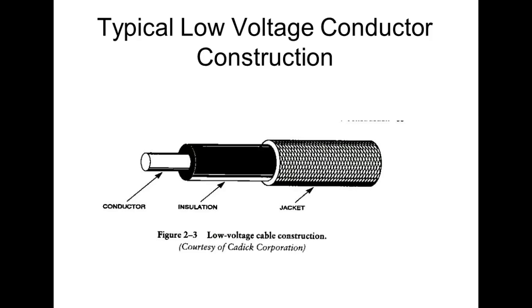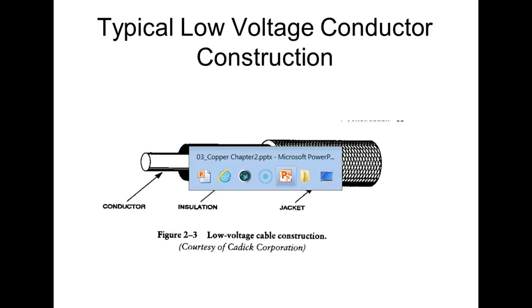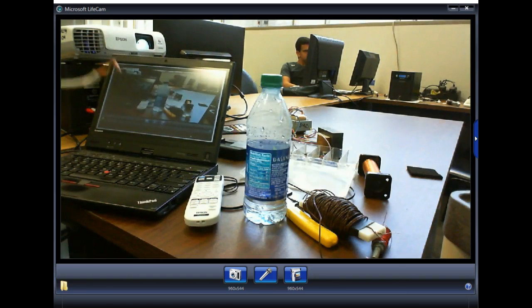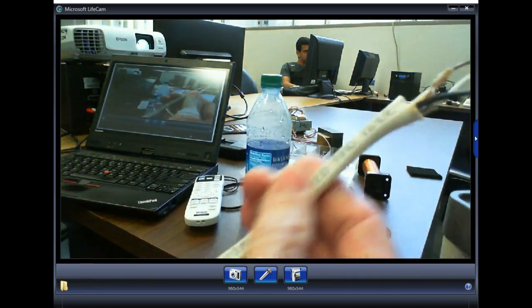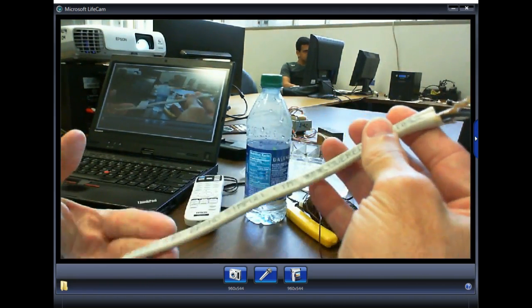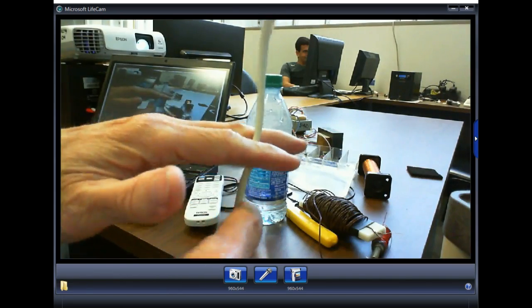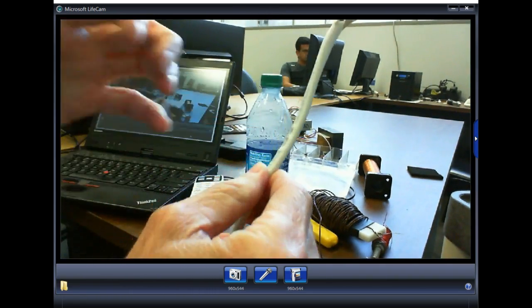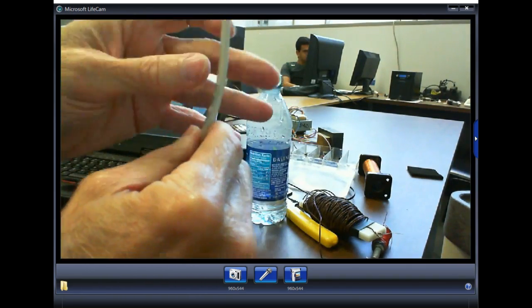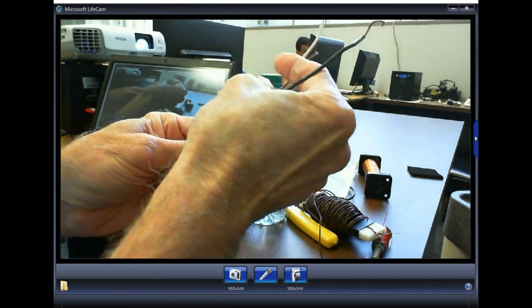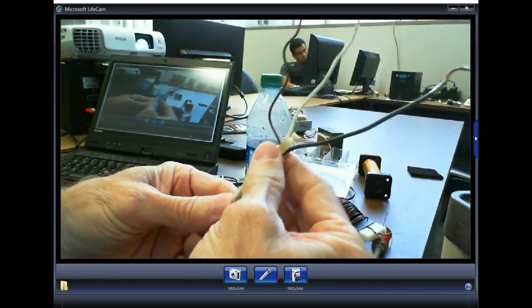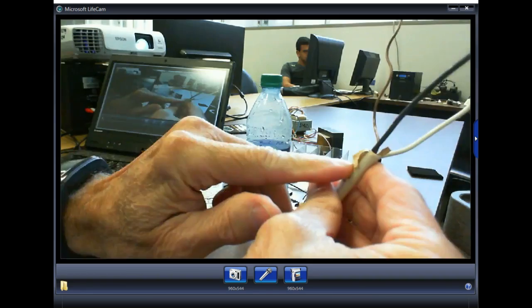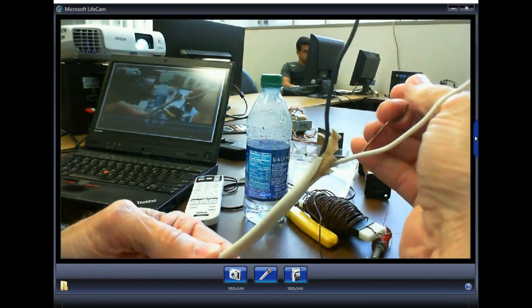So this guy is pretty neat in that it actually has a jacket. Because a lot of times when we get inside our box, we run it through our walls. You don't need to separate this while it's running through your walls. This protects us. We can use cable clamps. They come this size right here, where you drive them in, cable nails where you can drive them in and hold it and support it. But once we come inside the box, the pull boxes or the boxes, then we strip this jacket off. Here's the paper insulator. You'll see that in there for the ground conductor.